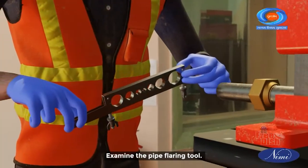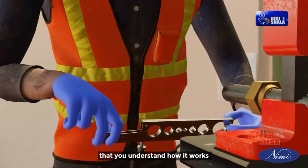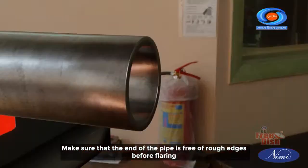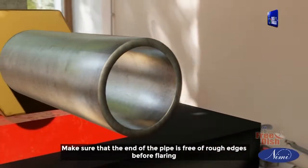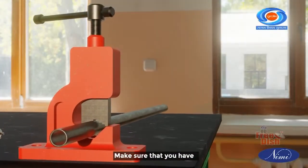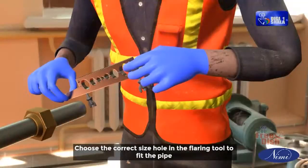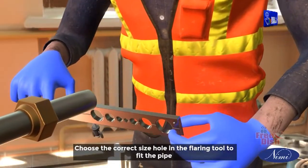Examine the pipe flaring tool. Make sure that you understand how it works before starting to flare the end of a pipe. Make sure that the end of the pipe is free of rough edges before flaring. Place the pipe in the tool. Make sure that you have placed the flare nut on the pipe. Choose the correct size hole in the flaring tool to fit the pipe.